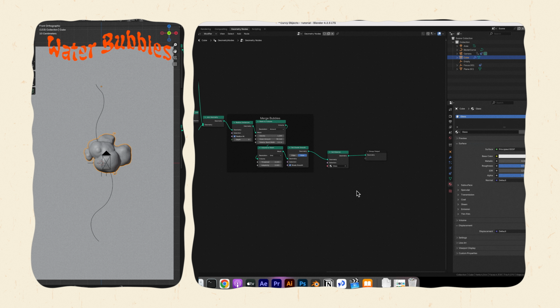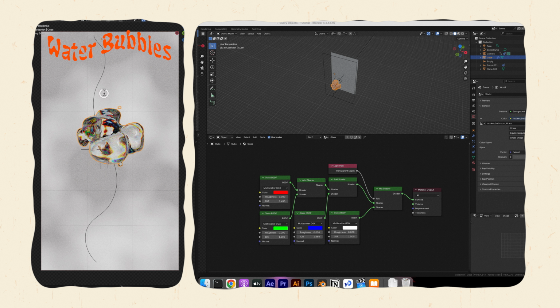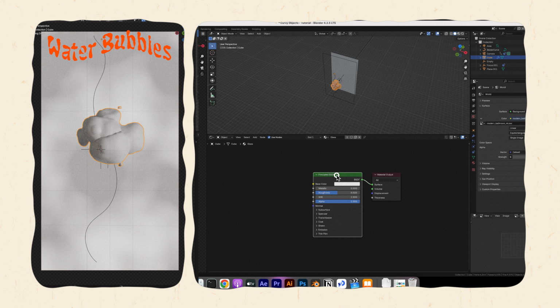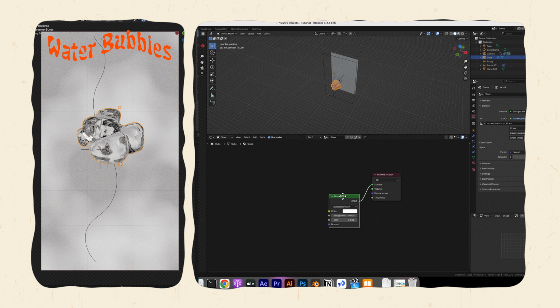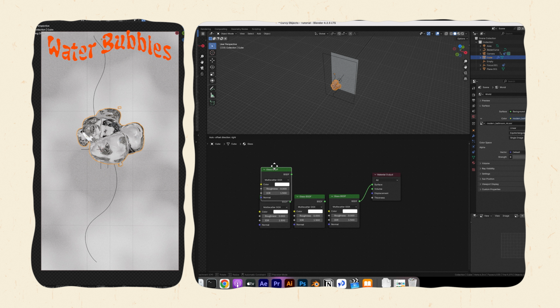I called it glass. This is the glass texture you'll see many Blender users apply, and it's quite simple. We'll remove the principled BSDF and add a glass BSDF instead. To add the dispersion to it, we'll need to duplicate the glass BSDF 3 times for the 3 color channels, RGB or red, green, and blue.